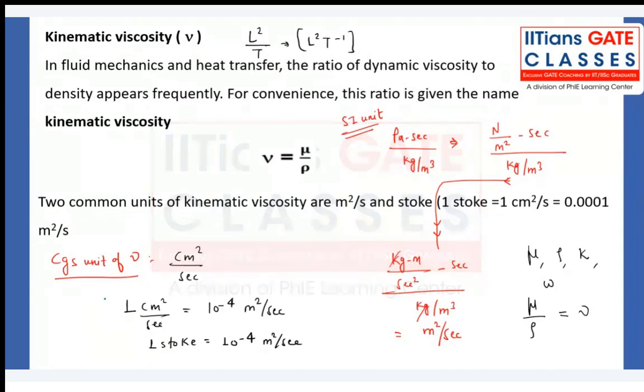So with the application of the external force, we are measuring that one. Which one? What you call dynamic viscosity. But in the kinematic viscosity, if I want to measure for any fluid, I will not directly apply the shear stress, right? It is just being rotated with the help of maybe some gravity. In that case, I will directly measure the deformation rate, and I will take the ratio of the actual dynamic viscosity of that particular fluid to the density of the fluid. So that will give me kinematic viscosity directly.